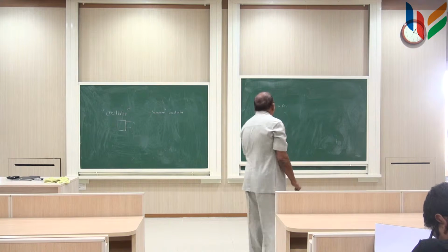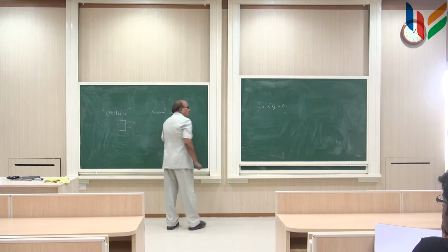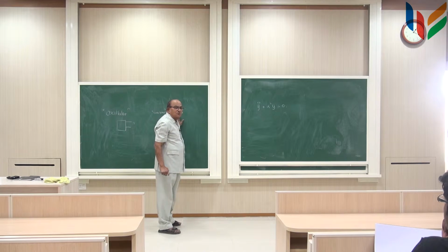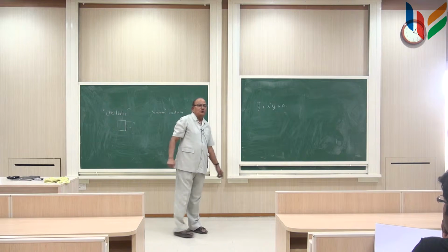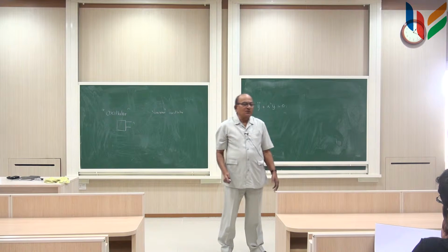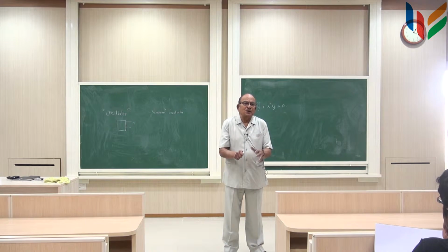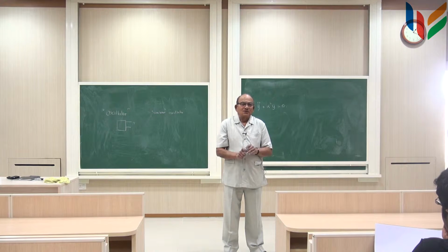So, now what I am trying to drive at is that the amplitude of this oscillator also must be stable, not only the frequency. This equation does not tell you how the amplitude is stable. Theoretically, the amplitude will grow up and up. Something has to keep it at a stable value. How does that happen?